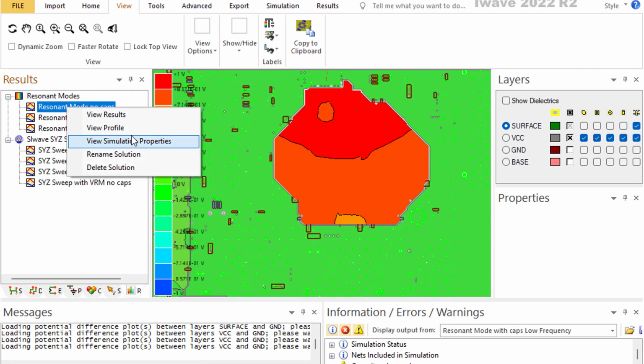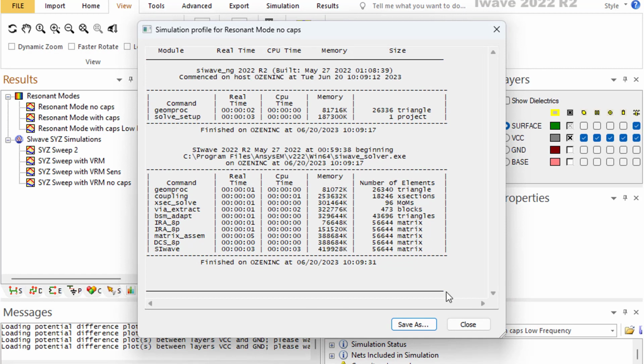There are other things that you can do, like look at the profile, of course, which will tell you more information about how much time was spent and the mesh size and all of this information. These are important when you are comparing the solution of two models, or you are comparing the solution of the same model at different times. It tells you whether the solver did something right, or whether the solution looked weird. For example, it took a faster time to solve. That doesn't make any sense. It should spend the same amount of time if it's the same mesh.